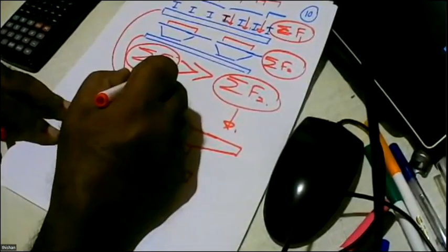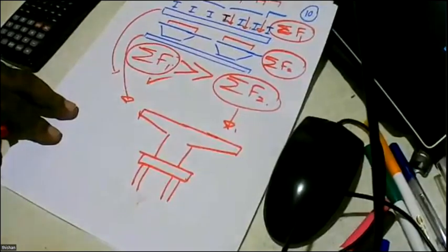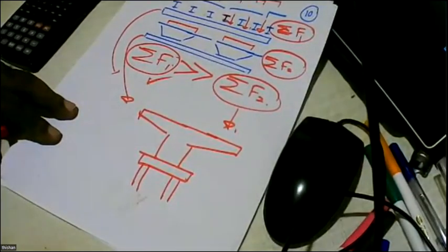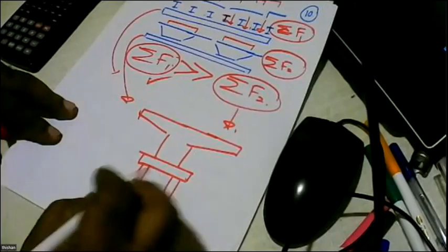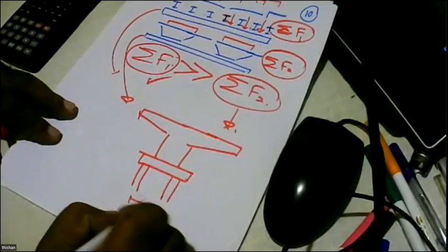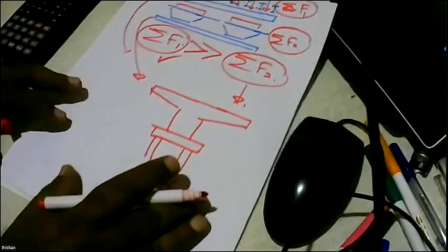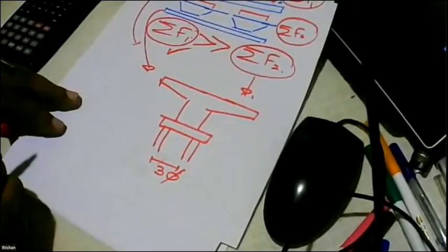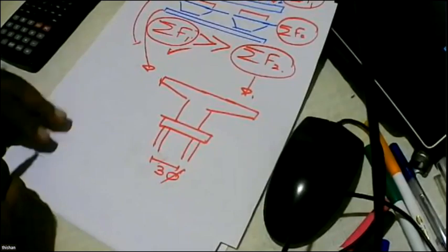So when you go with a lesser number of beams, you can end up with a lesser number of piles. When you have only few piles, and when they are at a spacing of 3 times the diameter, I think you don't have to consider the group effect.